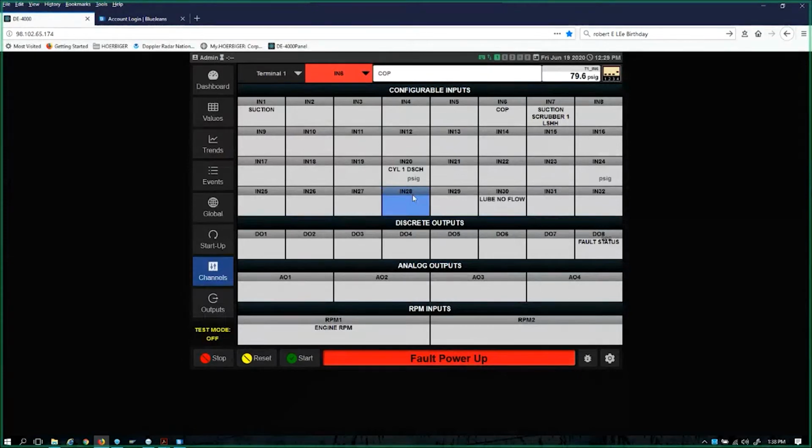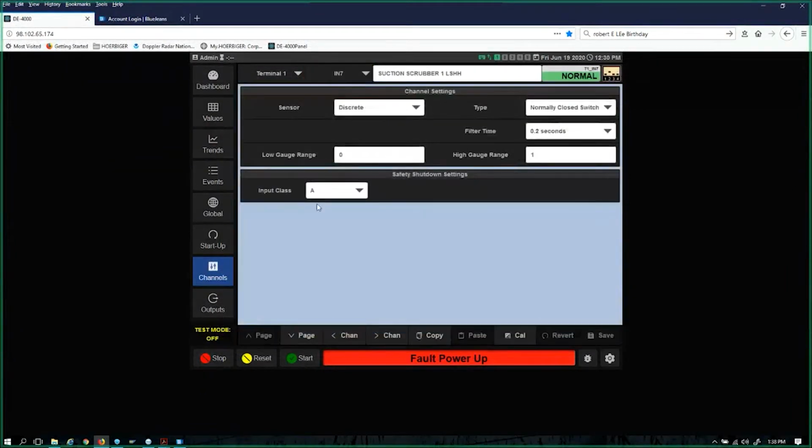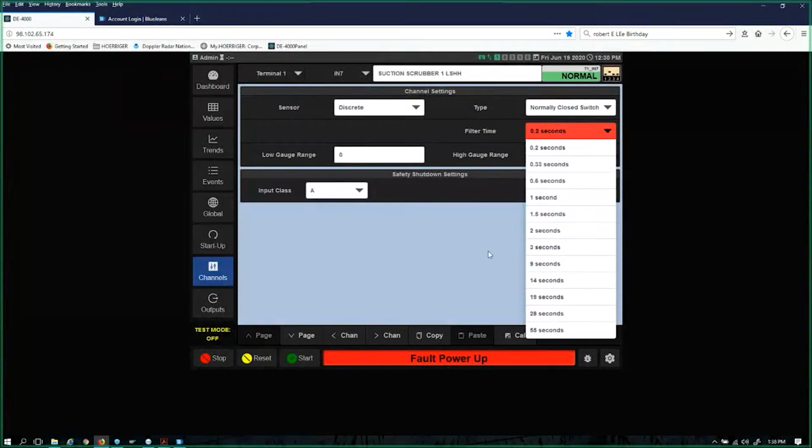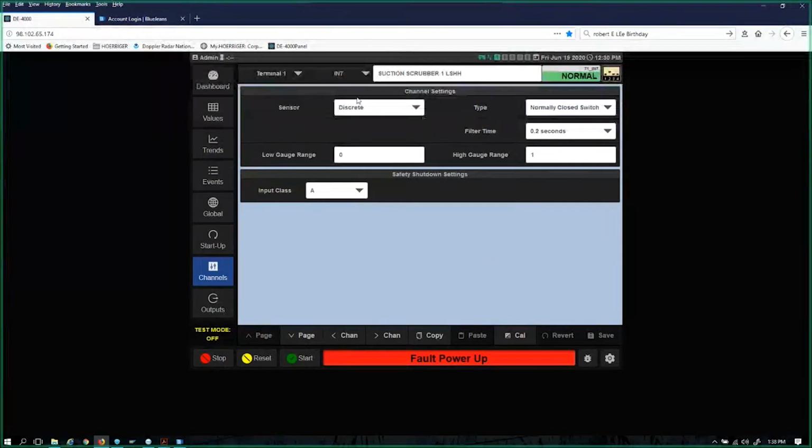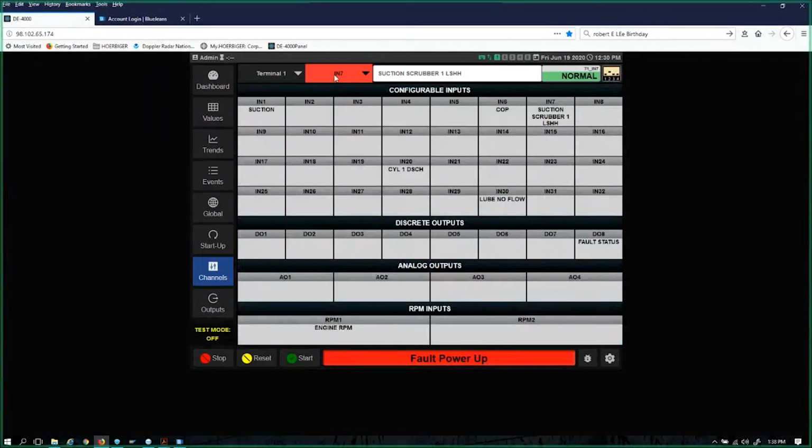So, yes. One thing that I talked about with a group of gentlemen was, say they had a little bit of turbulence in a surge tank up on top of a cooler section where we were monitoring a low water level shutdown, and maybe the float was bouncing a little bit. That's on a discrete channel. That's an excellent way to put a debounce in there. So the filter may filter out some of the artificial noise coming in, so it won't have all these little shutdowns that you possibly never see.